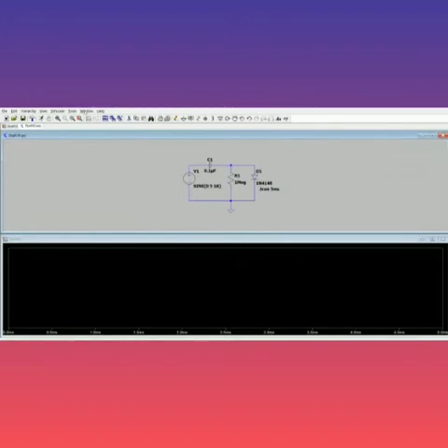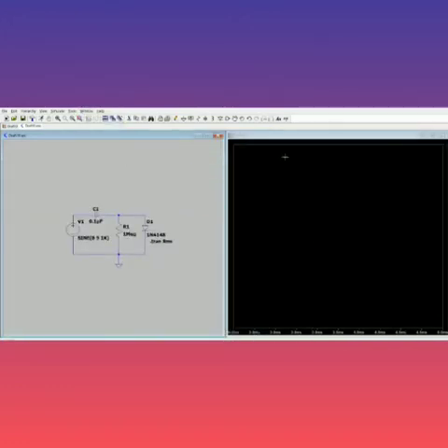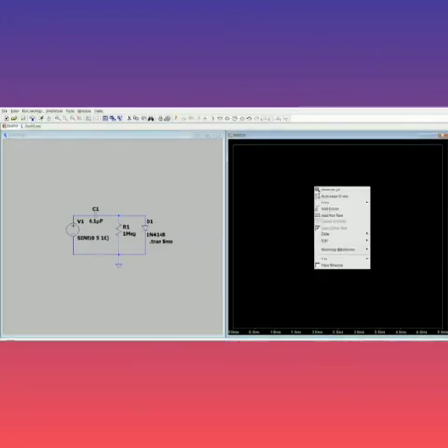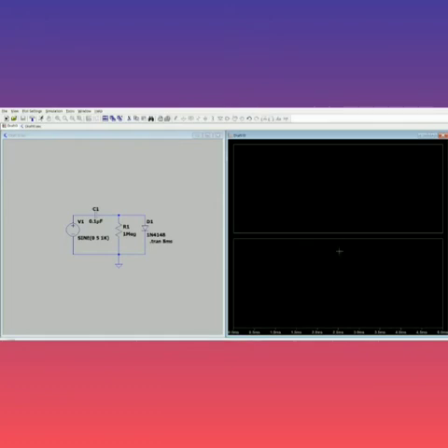So here I'm going to change this, that is go to window, tile vertically. Now here I require to see input and output separately. Do right click in this particular graph. So go to add plot pane so that two panes come. So keep your cursor in the first pane. Now again go to run option. So I want to see my input wave. So go and keep your cursor near the voltage.